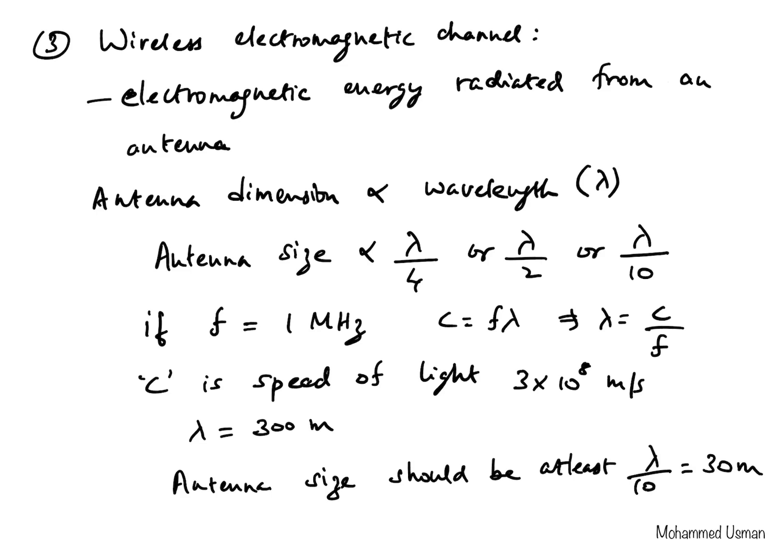Okay, now on a wireless channel, again, we're going to have the effects of attenuation, multipath propagation resulting in fading, and also additive noise, which is random in nature. So we have to deal with all these effects of the channel, even for the wireless case. Now, in contrast to the wireless electromagnetic channels, where we tend to use higher frequencies because we want to keep the antenna dimension small, there's another type of channel where it becomes more practical to use lower frequency to communicate, and that is what is called the underwater acoustic channel.